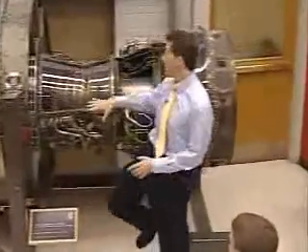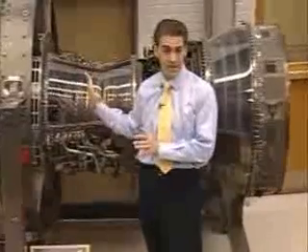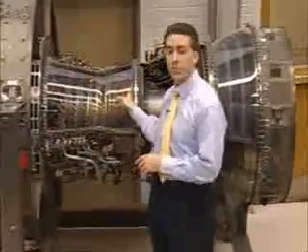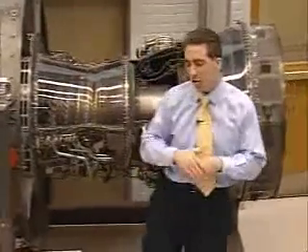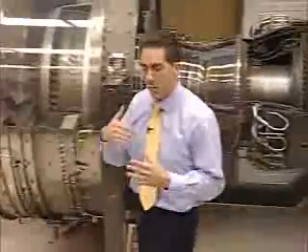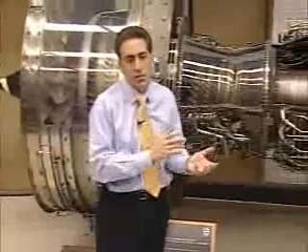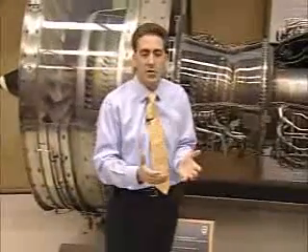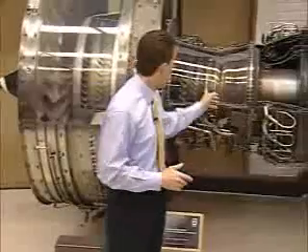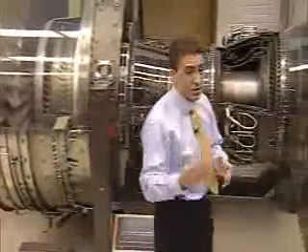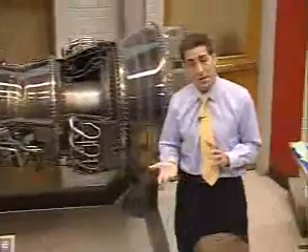You start out with a cycle analysis for this, so you determine how much pressure you need. Then you look back at your old engines and you say, for each one of these blade rows, how much pressure rise was I able to produce? And you know what those shapes used to be. And you know how fast you spun those blades as well. And how fast you spin them is tied to your structural capabilities of the materials.